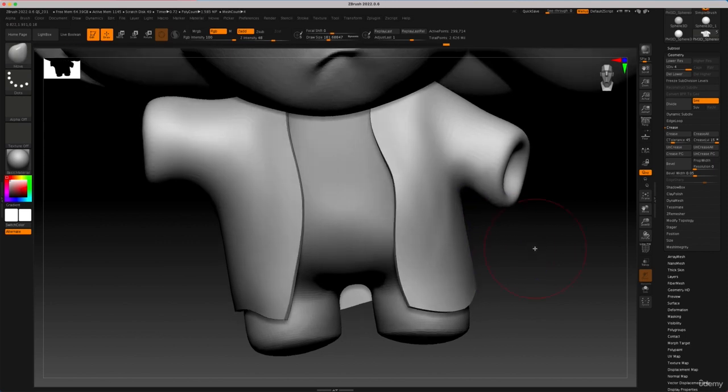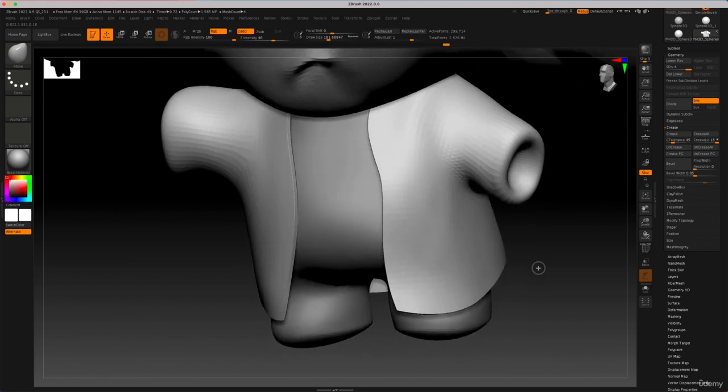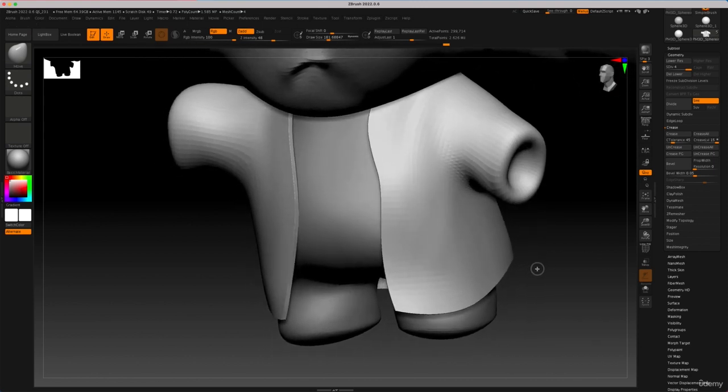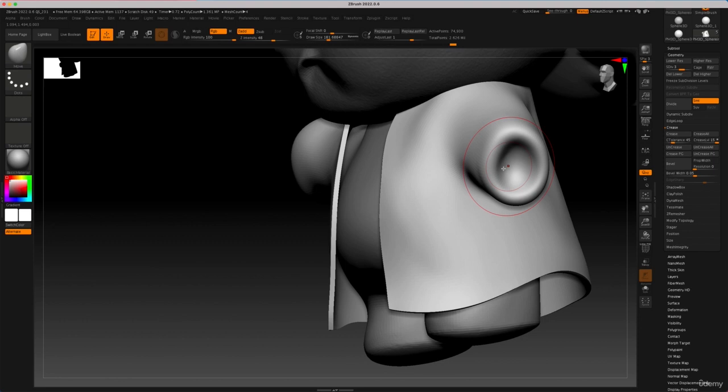And to do that, it would be much easier with the utilization of multiple subdivision levels. And if you're going to try and sculpt out tears with the knife curve brush, you're going to have to delete those subdivision levels. So I would save that towards the end, and try to get all the work you need done while you still have the subdivisions available to you.